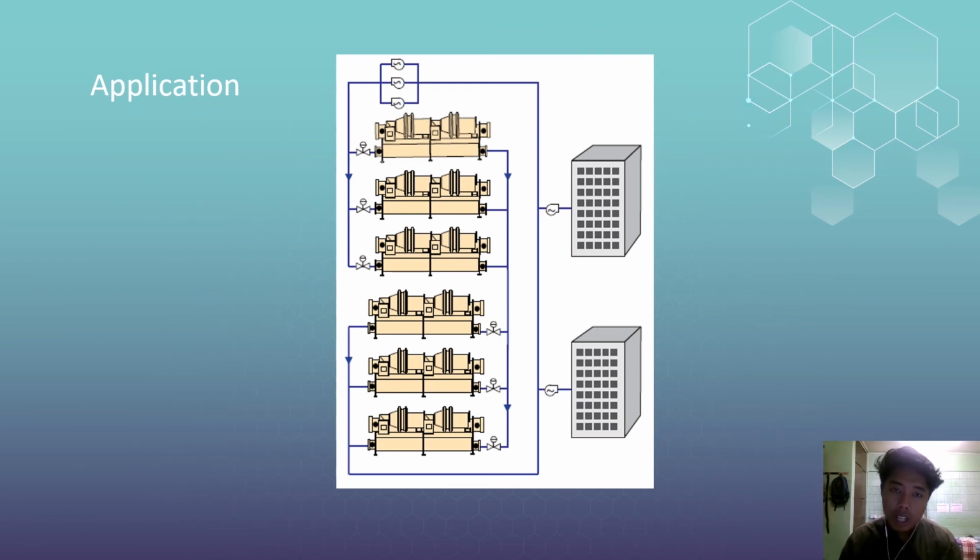In some locations, it is difficult to find enough fresh water to fill a very large system, especially if the chilled system is quite distant from the loads. Cooling towers consume water, which can be significant and difficult to obtain in some locations. The search for both locally available makeup water and energy saving can lead to the exploration of alternative condensing sources like lake, river, or well water.